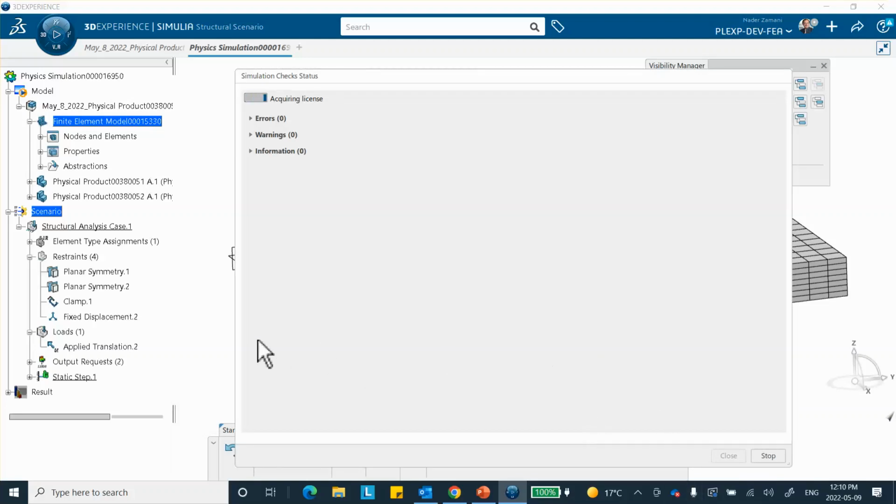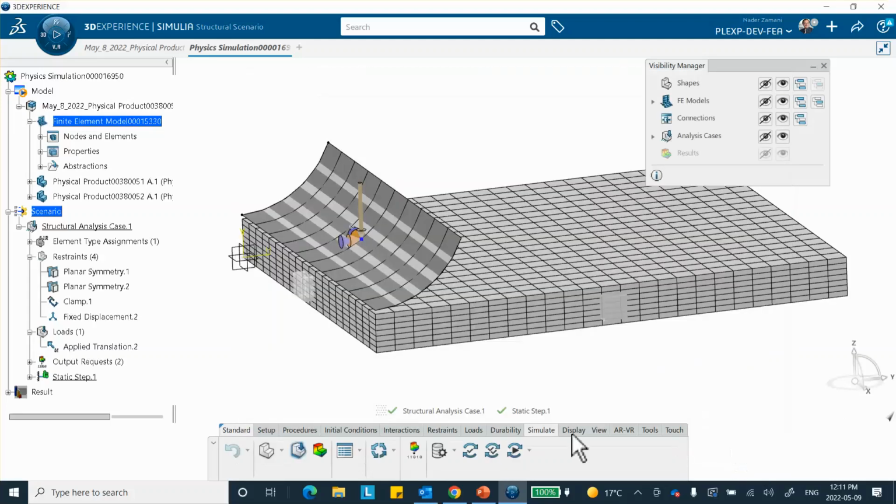There are no error messages here. But you will see that actually that thing will go through the bottom plate because there is no interaction defined between them. And we're going to come back and fix that. There are some warning messages. A good idea to read these things, but I'll leave it the way it is. Okay, good. And now we're going to run it.